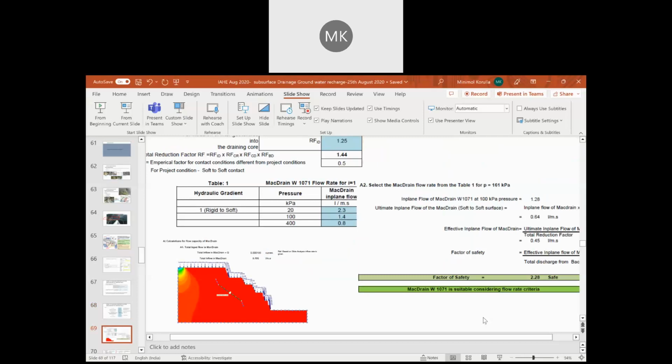So different types of drainage composites are there. It's not always the same type of geonet. The different manufacturers are making their own changes to define their brand identity. But what a designer or a client needs to address is the filtering component, then adequate permeability, then the retention capacity, the draining performance.